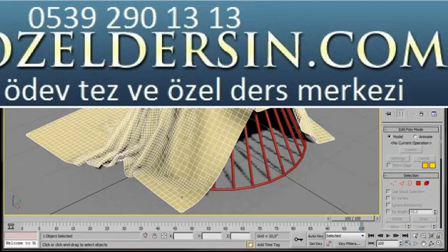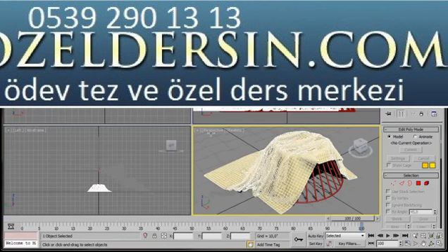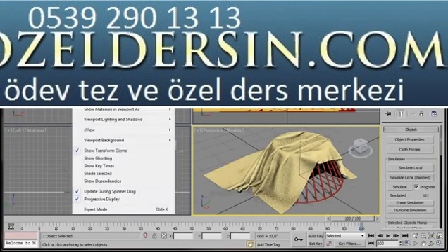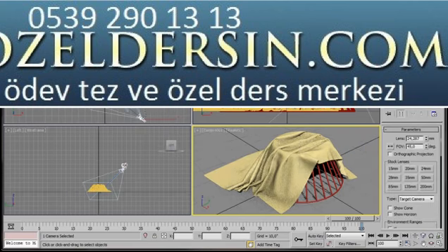Used it, so let's carry on from here. Press Alt W on the keyboard to go to all 4 viewports. Now we can go to our perspective view. This is the position of the image that I want when I render out, so now I'm going to go up to Views on the main toolbar and select Create Camera from Viewport.